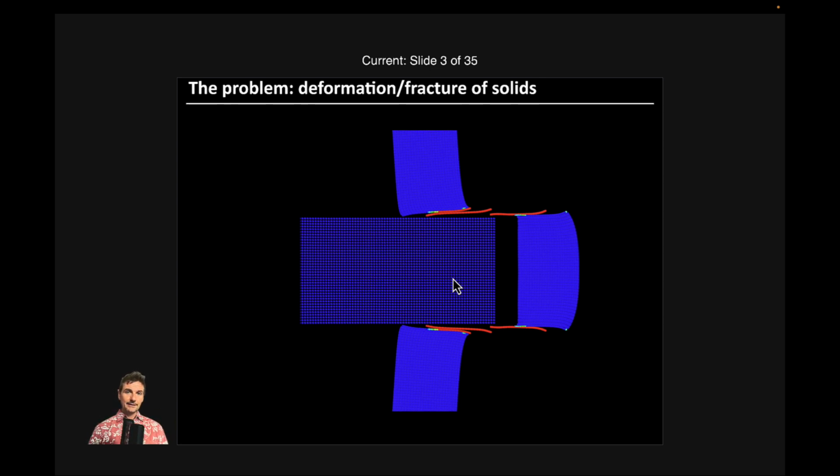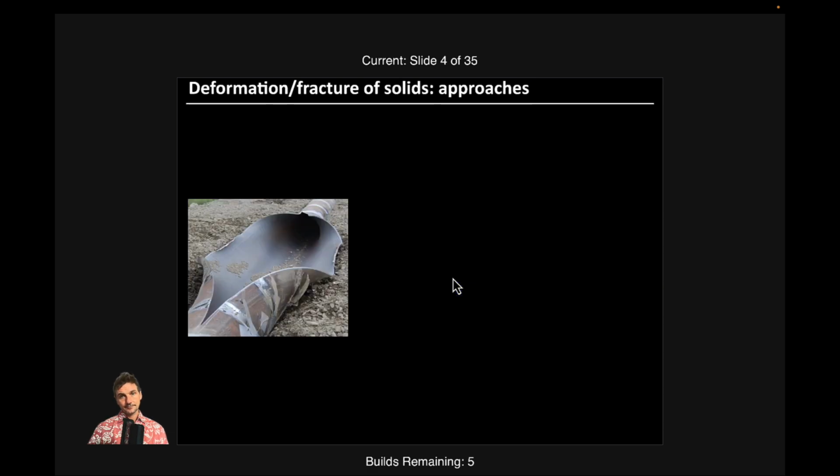So the idea of meshfree methods in that context is no longer to deal with fragmentation and things that split up into pieces, but really to have a solution which is high order continuous, enabling things like shell problems, shell elements, or maybe fracture problems, if you want to have higher flexibility in the way that you write the approximation scheme, so that you can reproduce any function. I will come back to that. So basically that's the idea of what you want to do with MPM.